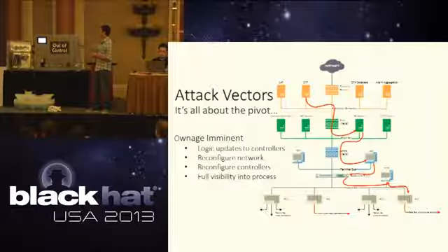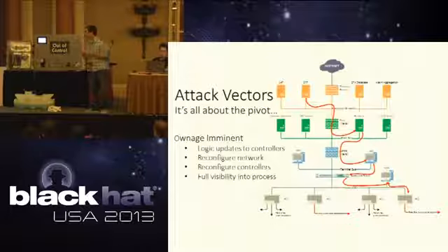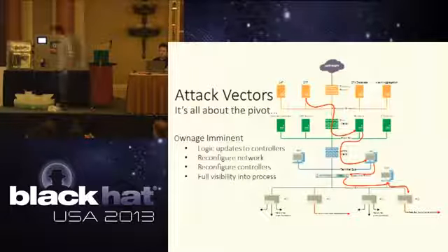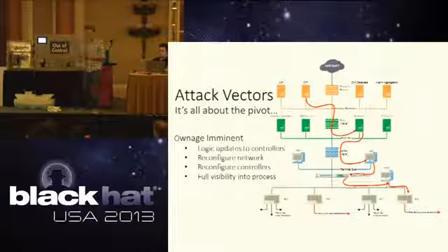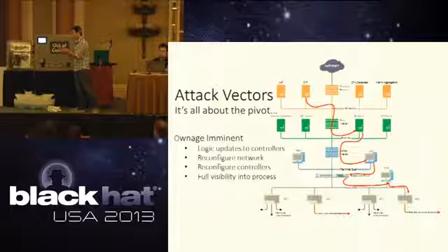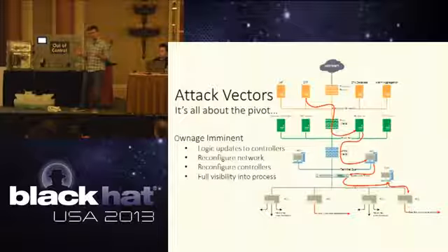But what you can do is if you're on an engineering workstation, you can actually steal the source from the controllers themselves. So you can actually get the logic files and modify the logic files on the PLCs while they're still online. And why that's important is because in the olden days, you had to take a PLC offline, modify the logic, and then bring them back up. But you don't have to do that anymore.